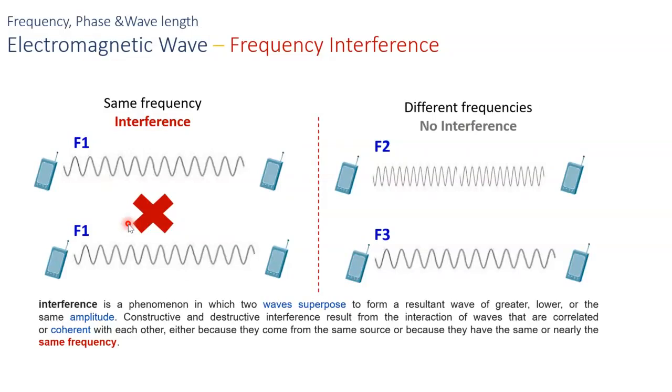So FDMA, which stands for frequency division multiple access, divides the frequency spectrum into frequency bands or channels, and each user is assigned a fixed frequency. Why? To avoid interference. Like in this scenario, user 1 uses F2, user 2 uses F3. So what happens when a frequency band is unused in FDMA? The unused frequency band goes idle.